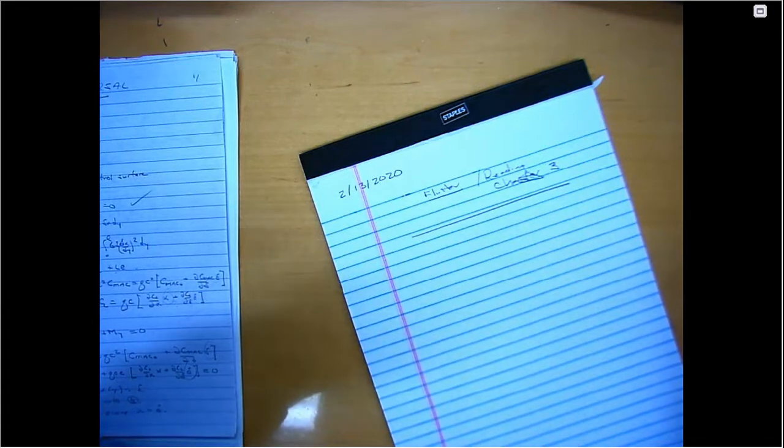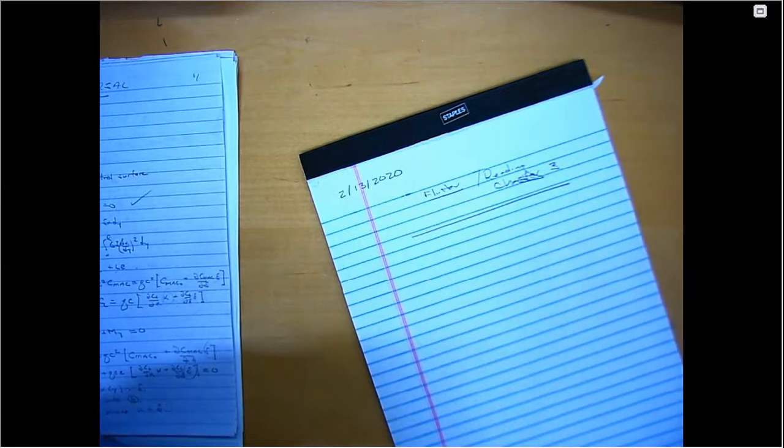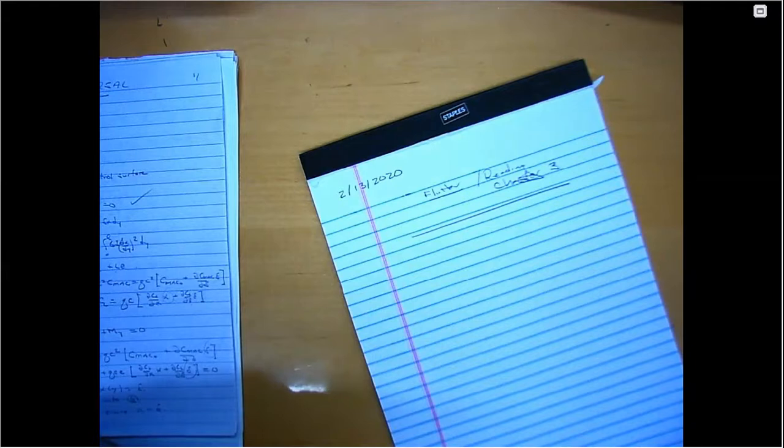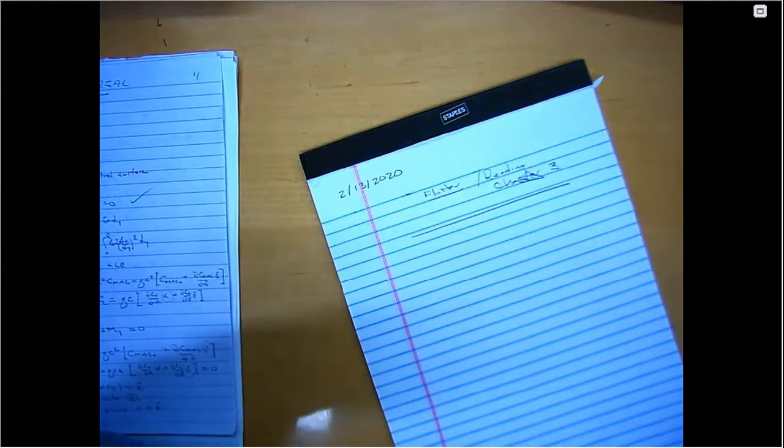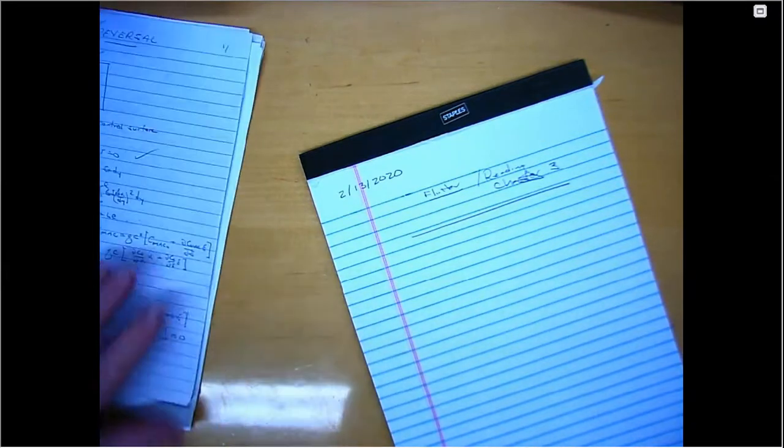And we want to discuss at the beginning of chapter 3 and the material therein, flutter and the physical phenomenon of flutter. There's a counterpart to divergence, which is a static phenomenon, which is the dynamic instability known as flutter. There's really no dynamic counterpart to reversal. Reversal is a static concept. I mean, you could do a dynamic analysis of reversal, but you wouldn't gain much.